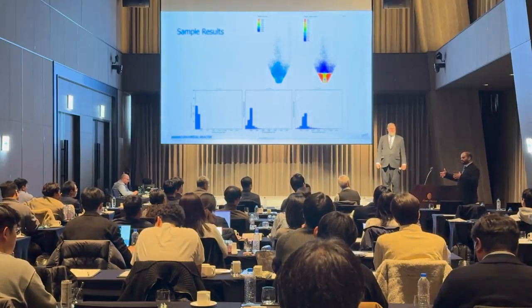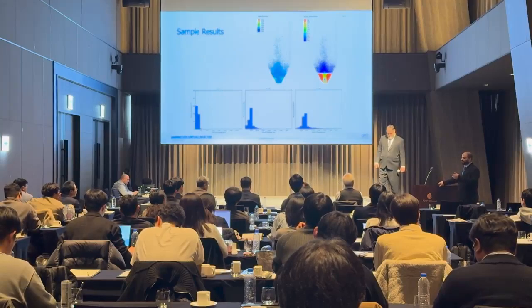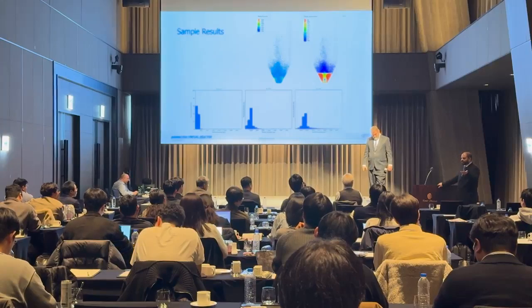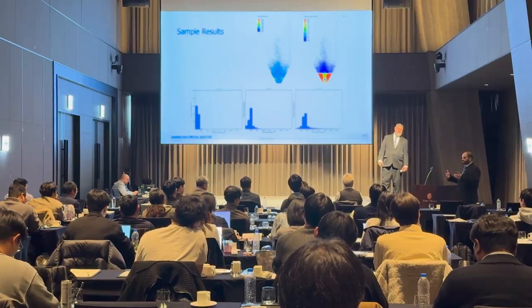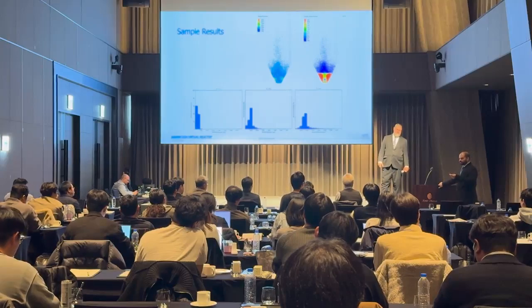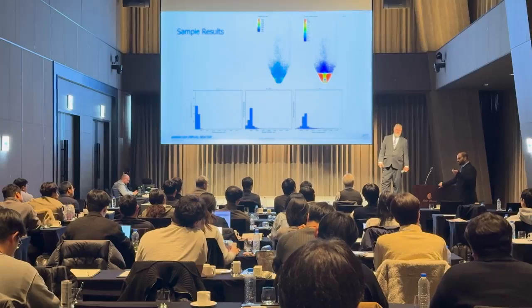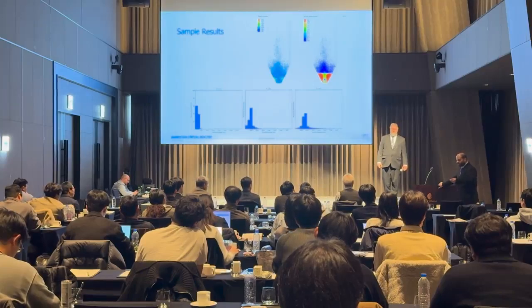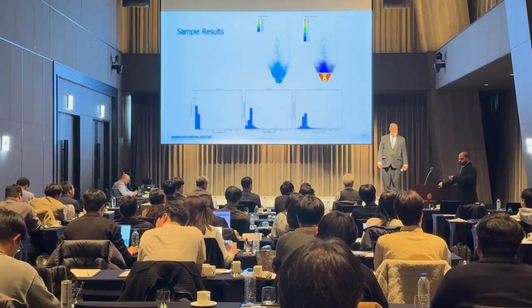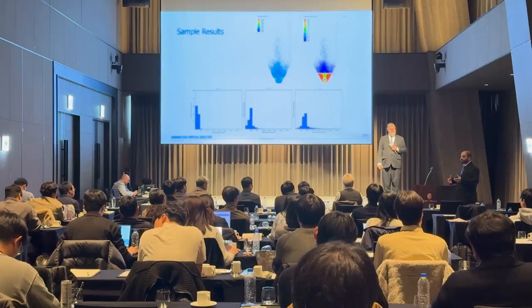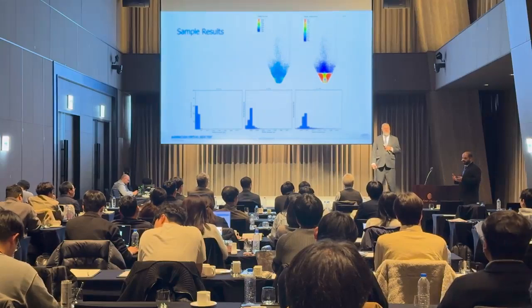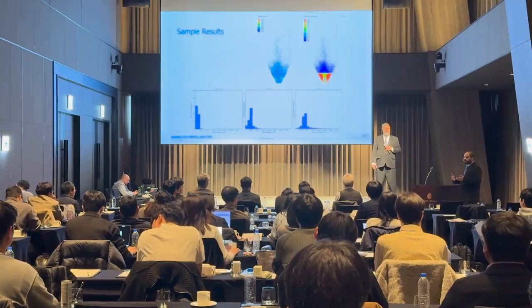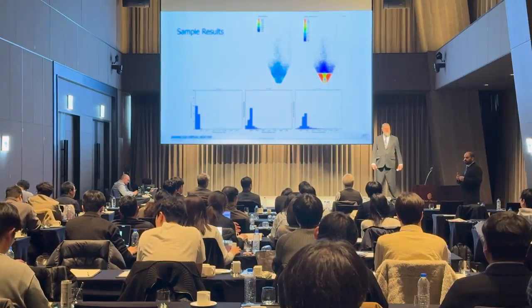If all those 1,000 reactions are happening simultaneously, then obviously the 200 will be faster than the 1,000. That's something to keep in mind. With CFD, we are not just purely solving for chemistry, we also have flow. So the user always has to think about what reactions are important. Can I get away with a 200-step process, or should I use a 1,000-step process? That judgment is still on the user. But there are very few CFD solvers which can handle 200 reactions, and do so stably. That's the key point here. Running a simulation stably with 200 reactions is a very stiff problem.